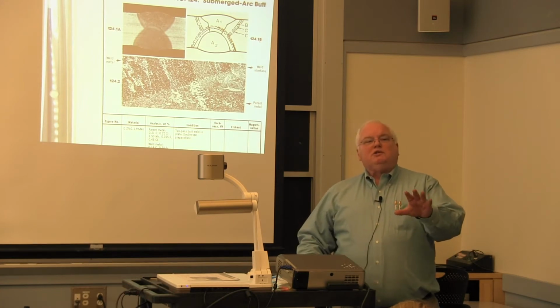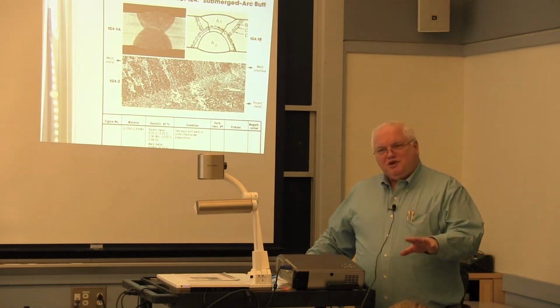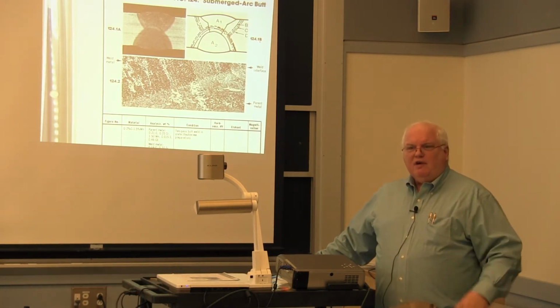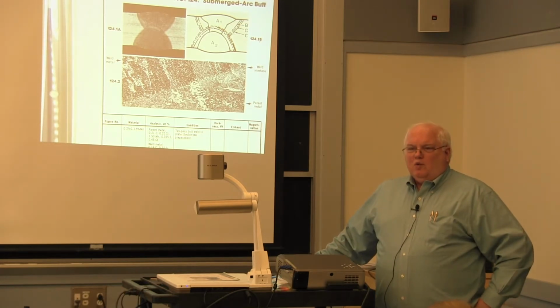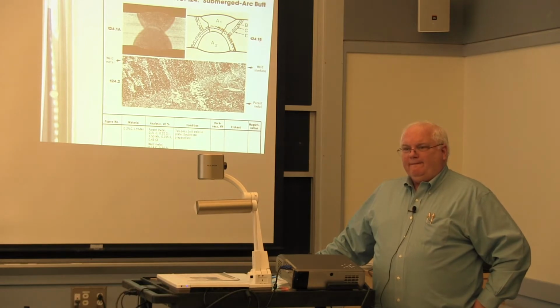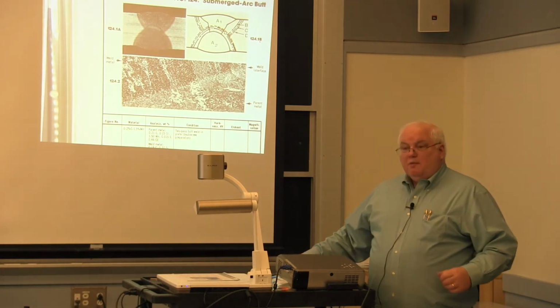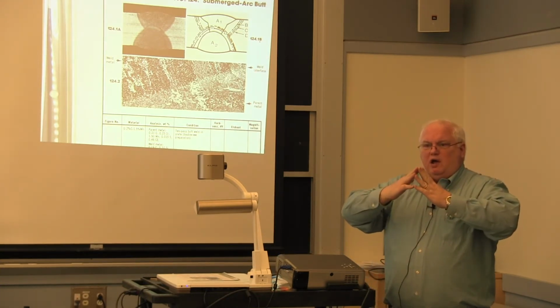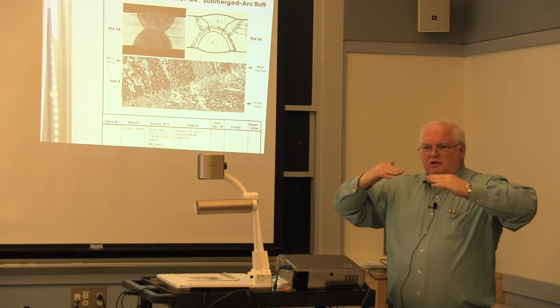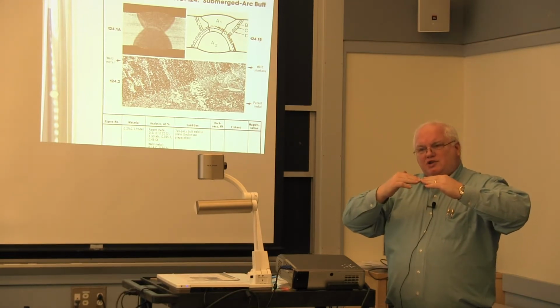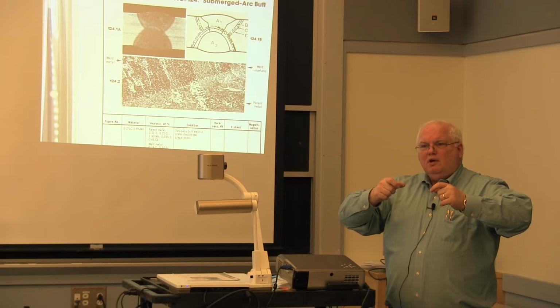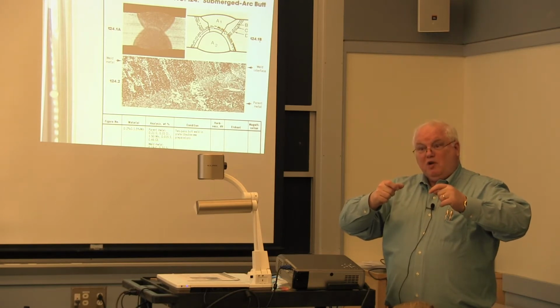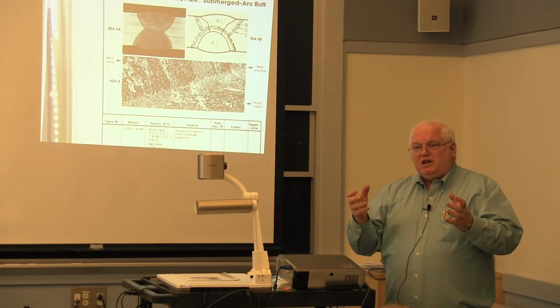You mechanical engineers out there, or you materials engineers, do you know why I would rather have a structure where the weld is slightly stronger than the base material? You're welding at stress concentrations, and because you're at a stress concentration, a corner or something, if the thing gets loaded in any way, whether it's bending or if it's tension, if it's undermatching, you're going to pull the weld metal, and it's going to yield before the base material.